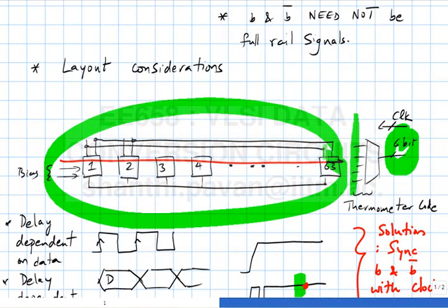One problem with putting things in a line like this is that if the number of cells becomes larger and larger, this will run from here to Timbuktu, right? It doesn't seem as attractive as it seems with 4 current sources when you see, say, a 10-bit thermometer DAC, in which case this will be 1024 current sources and it becomes a bloody nightmare. So anything that you think you'd be able to do?